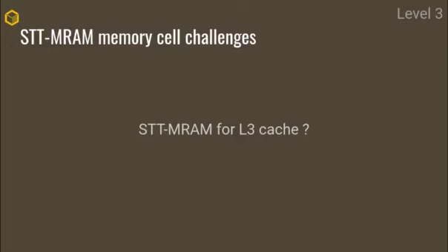Okay, now this isn't actually all grim. STT-MRAM has interesting properties, not for all types of MRAM, but it would potentially be very interesting for level 3 cache, because level 3 cache, unlike level 1 and level 2 cache, doesn't have to be as fast. It still has to be extremely fast compared to DRAM, but we can spare a cycle or two.